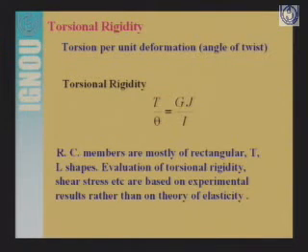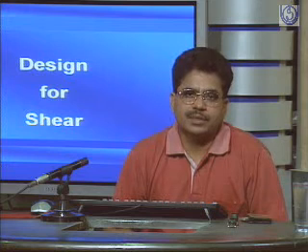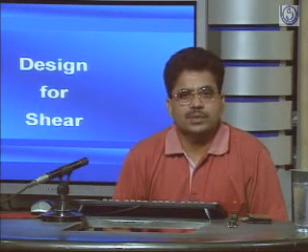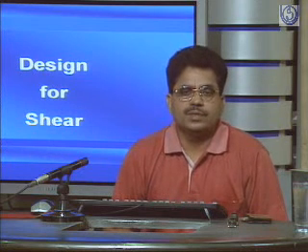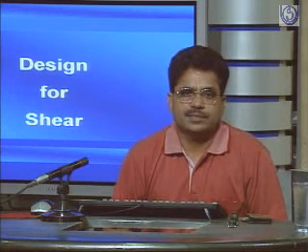Because for these shapes, rectangular, T shape, L shape, determining the torsional rigidity, shear stress and other parameters based on the theory of elasticity is very difficult, very cumbersome to calculate. So we go for experimental results.